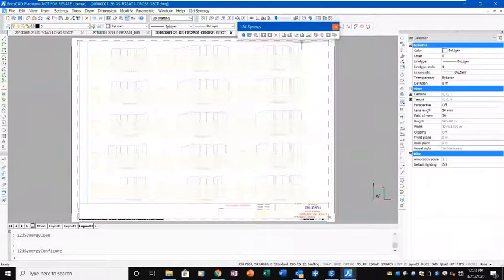All right, a few of the other toolbars here for inserting attributes. So instead of using a CAD attribute, you could insert a Synergy attribute instead, and then the refresh attributes as well. So that's for your Synergy attributes. The last button is if you are in a drawing and you've updated the Excel register, you can tell it to update from the register there as well. All right. But that's pretty much it for the CAD plugins.